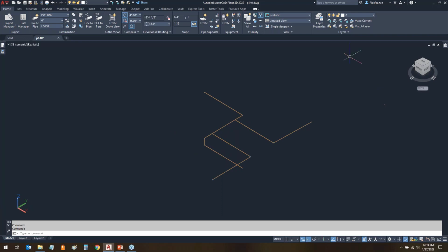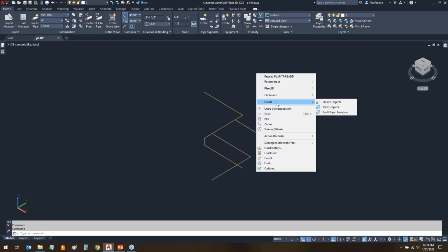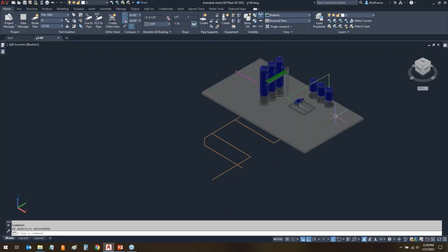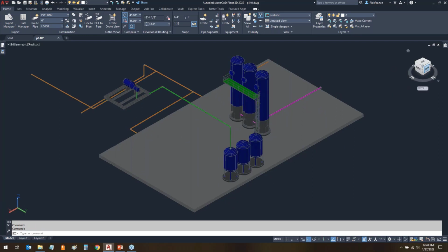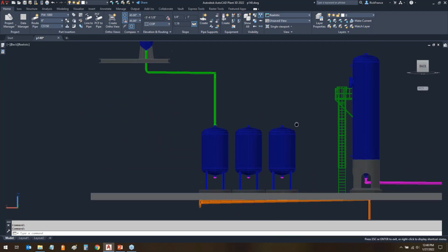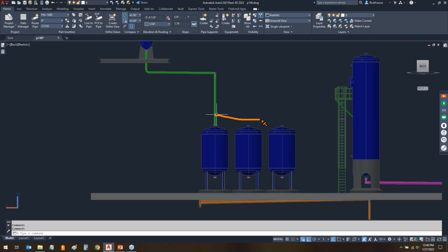The next part that we want to cover that was in our outline is vertical connections. In other words, let's go over here to these tanks. Let's say we want to have a header feeding these three tanks. We already got one in here. We want to have a header that feeds the next three that is sloped. I also want to use as little pipe as possible. So I want to be able to have a flange with an elbow and then come back this direction and then connect up to that vertical connection there.